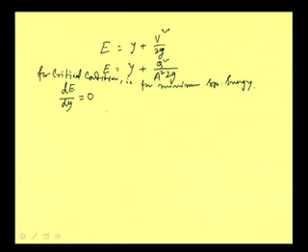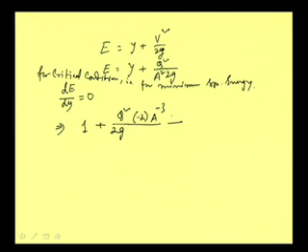And so, what is dE/dy? This implies it is 1 plus, then area is actually a function of y, so we can just differentiate it. If we differentiate it, then we can have q square by twice g, let it be, then A to the power minus 2. So what we will be getting is minus 2 into A to the power minus 3, that is the differentiation of 1 by A square, and as we have used A as the variable, we will have to write here dA/dy.